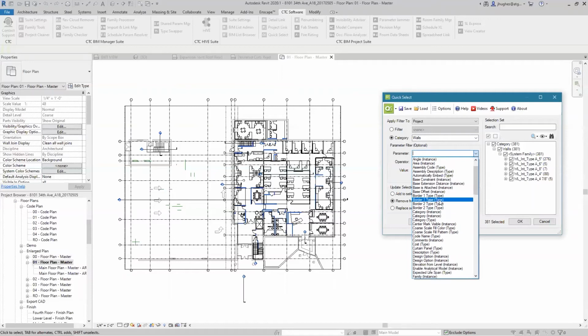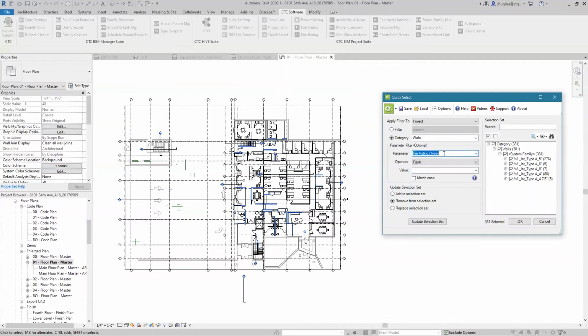And that kind of granularity is nice because Revit doesn't ever really spell it out for you unless you're over here. But we're going to look for fire rating. So we're going to make a selection of walls that have a fire rating. And now we can choose language modifiers here for, in this case, not greater than, equal to, because this is text, but is equal to.